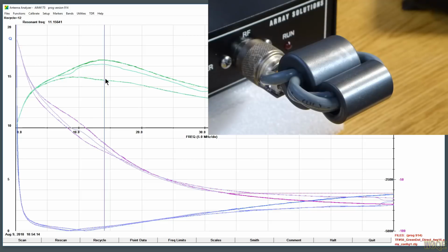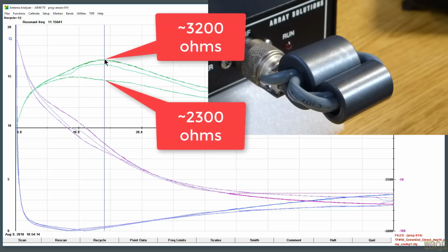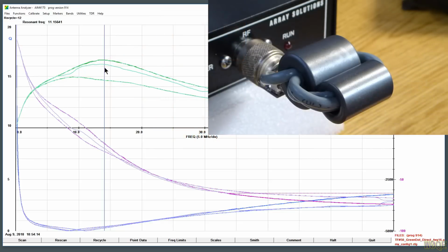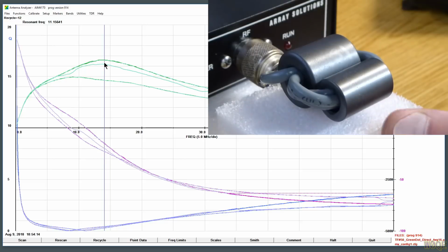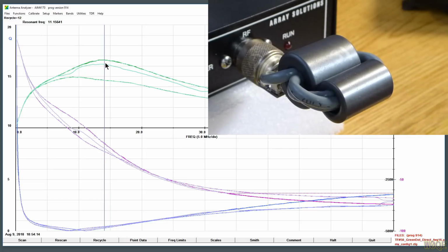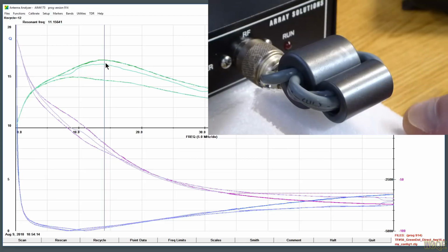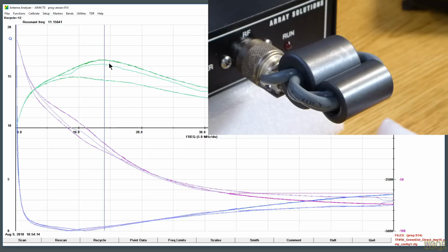Now the difference here, due to my body, the capacitance of my body, and the fact that these are incredibly high impedances, means that you probably won't be able to achieve these kinds of numbers unless you spend some serious effort trying to isolate this core from whatever, such as putting it on some kind of a pad that has pretty much basically air in it. These are like a high-density foam. They work pretty nicely, or something else. But if you let this core sit on a table or a desk, or sit next to other wires, you will not be able to achieve the value you measure.